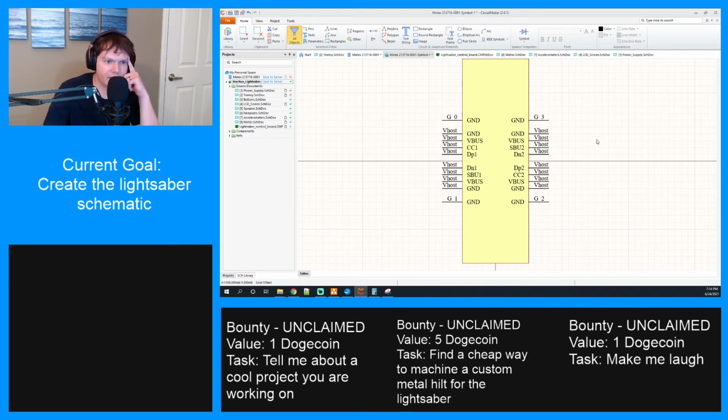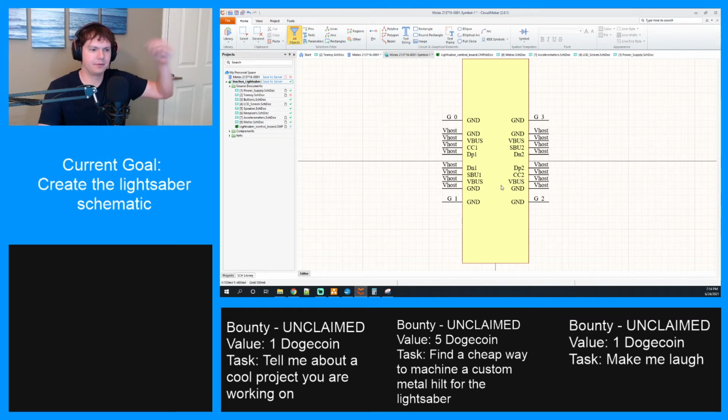So note that USB-C, you can plug it in either way and it's the same. And note how these pins are like CC1 is directly across and diagonal from CC2. And the same thing with the data lines. Data positive 1 and 2 are across from each other. All the VBus lines are diagonal from each other. So basically, if you were to flip it over, your data positive is still plugged into a data positive. Your CC is still plugged into a CC. It's just the other one. And your chip, the machine talking to it, can figure that out if you put the support in there and know which one number 1 is plugged into, which one's number 2 is plugged into, and just cross the circuits. So neat stuff.